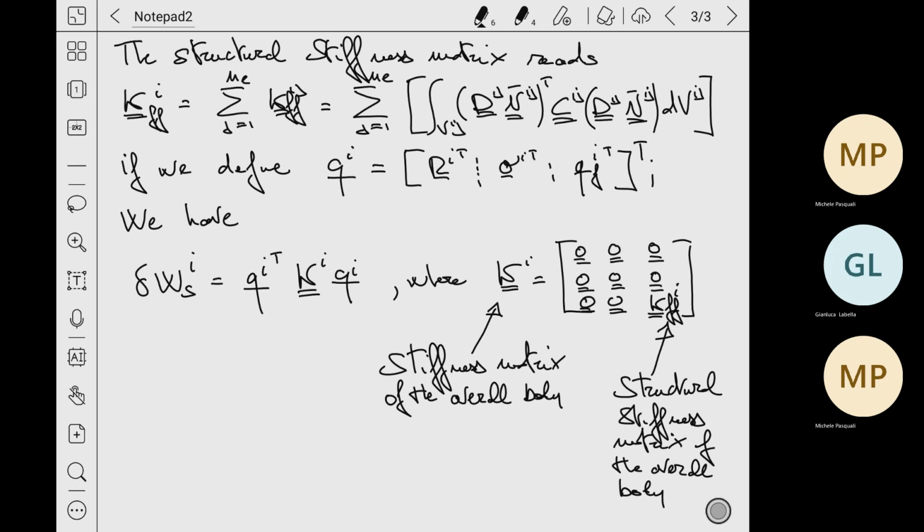So once you integrate it, your K matrix is constant. While M, as we have seen, can change a lot. It has a dependence on the Q's. If you do the same representation in the absolute nodal formulation, you would see the opposite. The mass matrix would be constant, the stiffness matrix would be highly nonlinear.